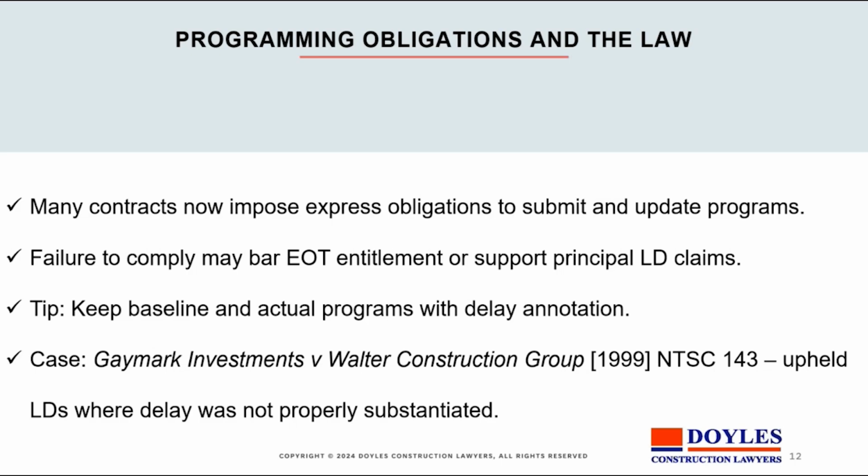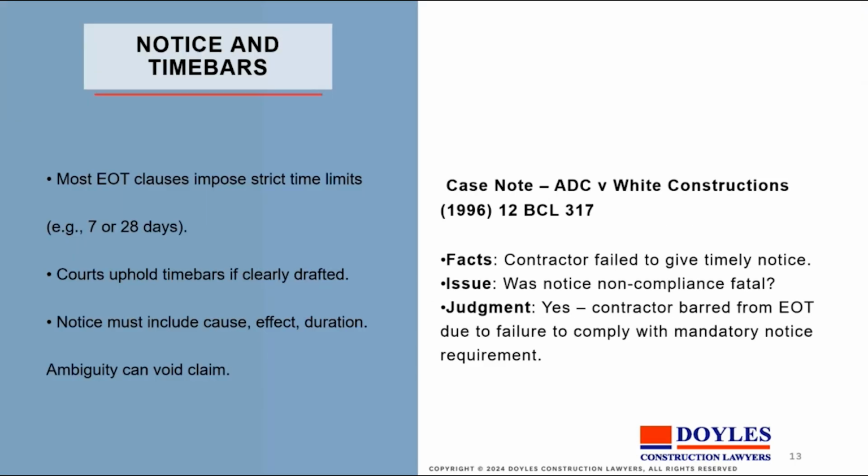And you've got to remember that in the programs you present, you must be careful to make sure that all critical activities are identified as critical activities. Otherwise, EOTs will be much harder to obtain in the future.